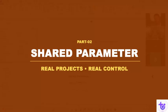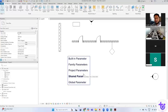Now it comes to the shared parameters, because the requirement was to have a parameter which has a scope across the project and the family. Even if we create it in one family, it should appear in the schedule in the project. Also, the same parameter can be tagged, so that means that particular parameter can be accessible in the tag family itself.